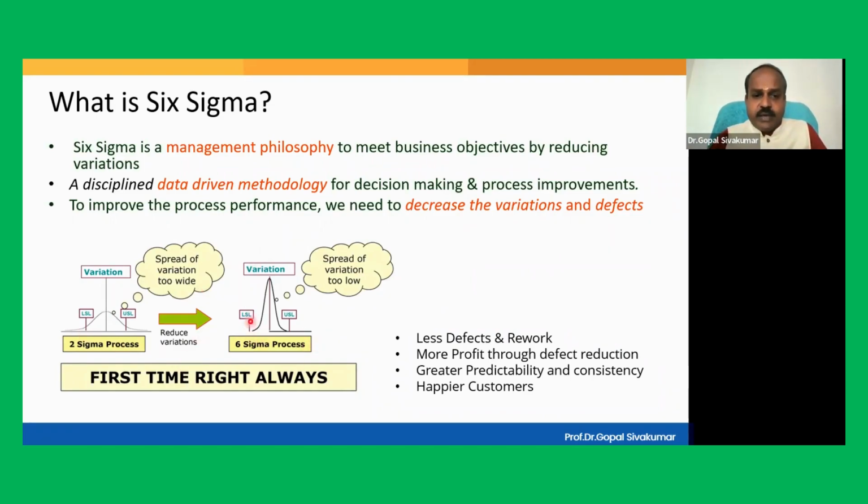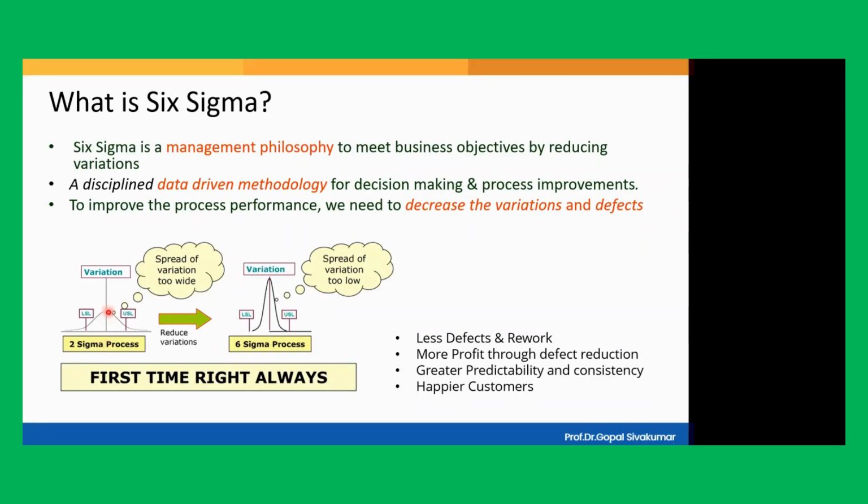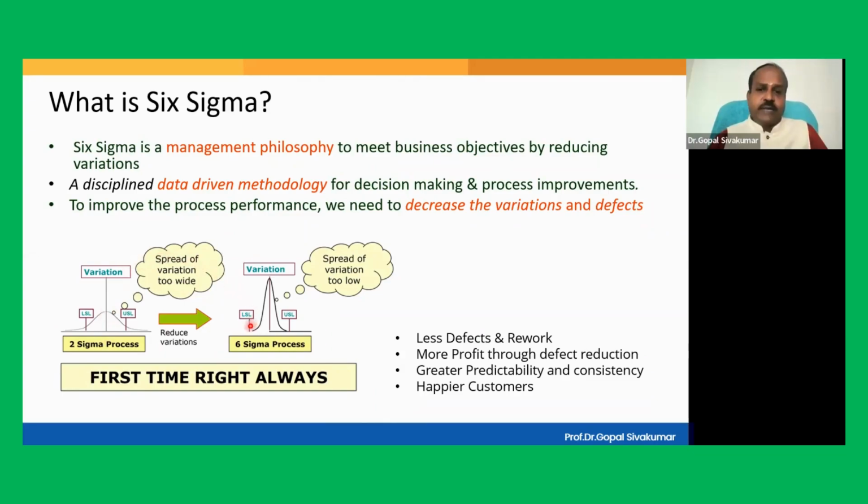The 40 will be here, 90 will be here. So what is the average score? Somewhere around 65. Am I correct? Many of the students would have scored around 65. That is why the curve is taking a peak around the average. Can you all see that? The curve is peaking at around the average? Yes. So if you take care of your average, and if you can also take care of the spread of the process, it is as good as preventing the defects completely.